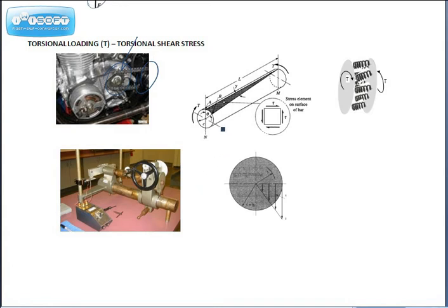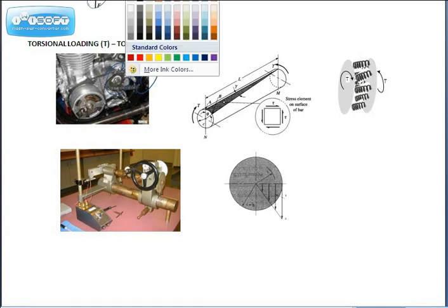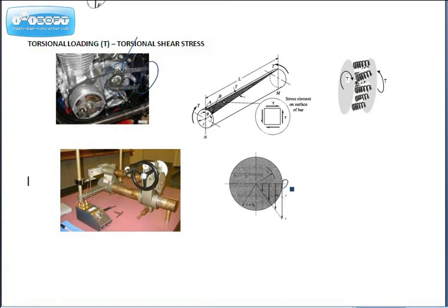And it too applies a stress to the material, and the way the material responds to that is by trying to rotate around its own center with an amount of stress that is greater at the outermost fiber. So as the material tries to rotate around its center, we worry most about the molecules at the outermost fiber because it has the most stress.